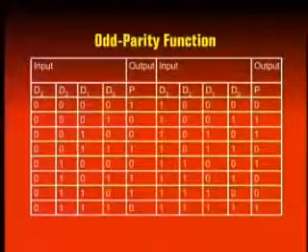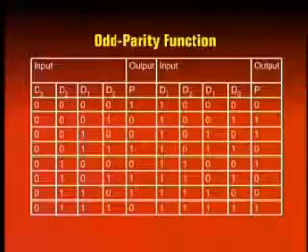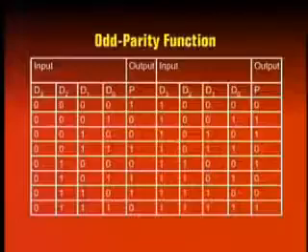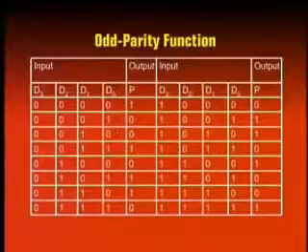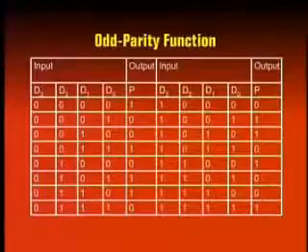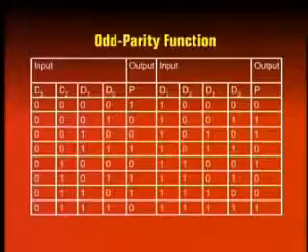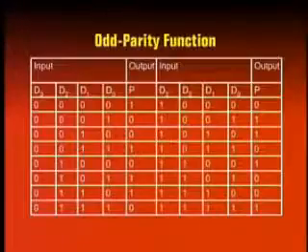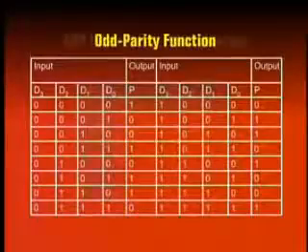The function table represents the 16 possible combinations of 4 data bits. The 4 data bits are represented by variables D3, D2, D1 and D0. The output P represents the state of the parity bit. Since odd parity is being used, the 4-bit data and the parity bit should add up to give an odd number of ones. The function table shows the parity bit set to 1 when the 16 4-bit data input combinations have no ones or an even number of ones.